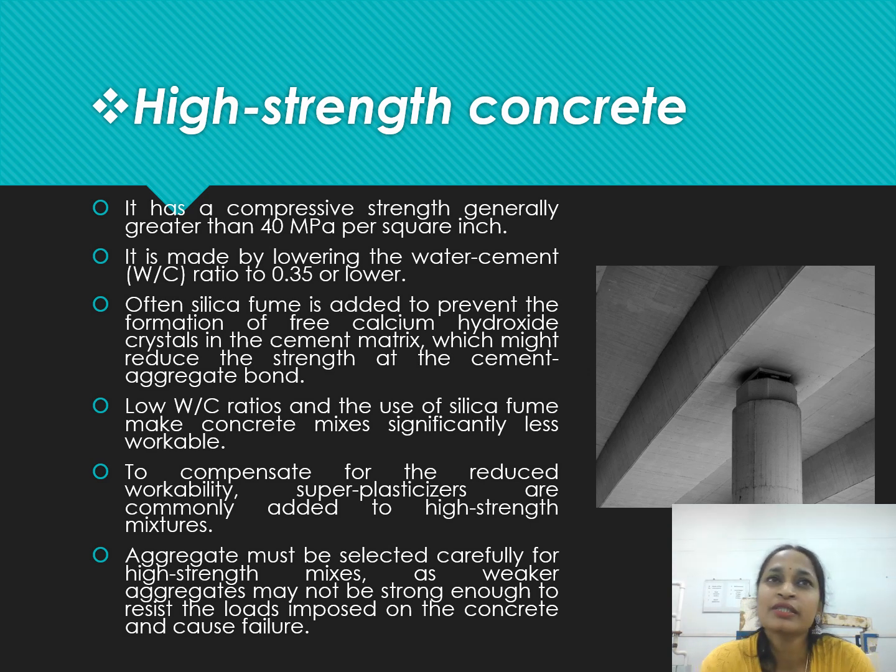Now, what is workable? Workable means being able to work with it. It means you have the ease to place it into the skeleton you want the concrete to be in. So you are able to work with your concrete easily before it attains its initial setting time or the final setting time, that is, before the concrete loses its plasticity.